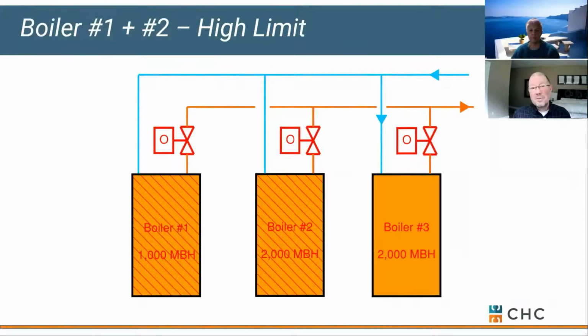So you've got an owner with 3 boilers in his mechanical room, and unfortunately you can only fire 1 boiler at a time in this scenario. That's the problem with direct return. If you had this as reverse return, we would be flowing in from the left to right, and we would have balanced flow across all 3 boilers. So when we open one of their valves, they would all be getting the same water flow. Okay, that's important in order to keep our boilers online.